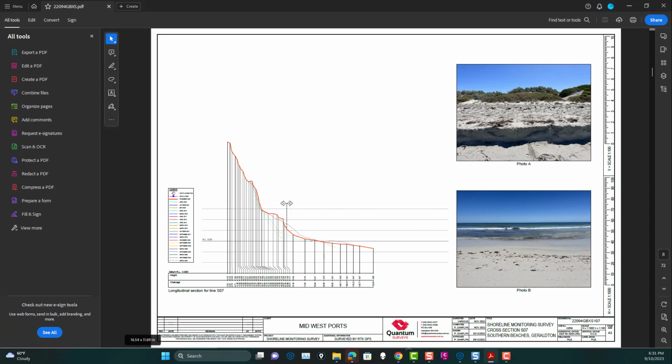So in this case we've got the drawing outline, the title box borders, we've got our profile drawings, and then you can add photographs if you like for the photo points, and then this is the photo point marker that's placed here. And then you can superimpose previous years' profiles or previous surveys' profiles onto the same drawing, and then put legends on the drawing and stuff like that. So you can produce high quality drawings exceedingly quickly within the TBC environment, and have a high quality of output as you see fit. That's the new Linestring by station command.